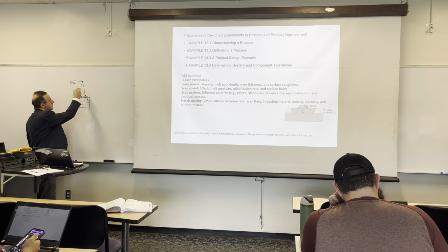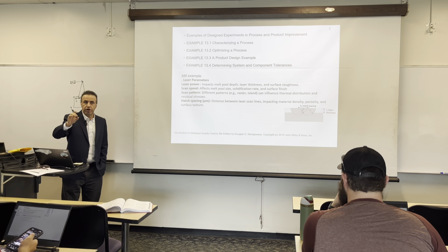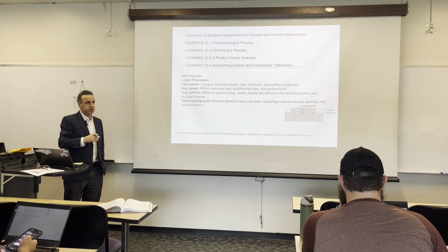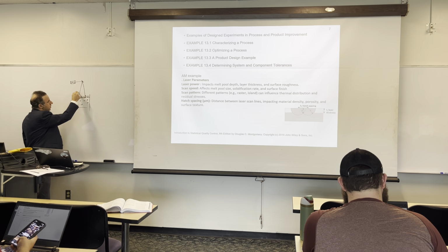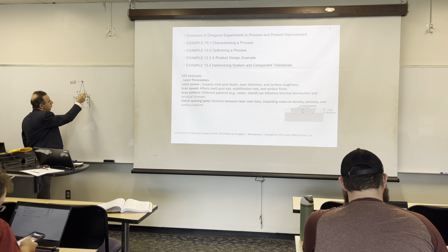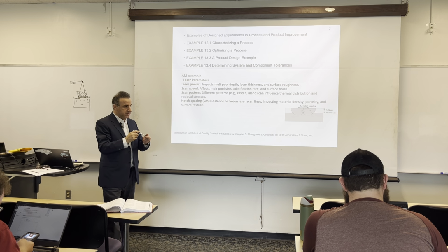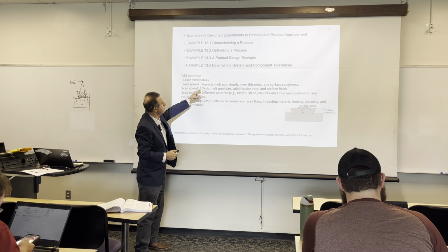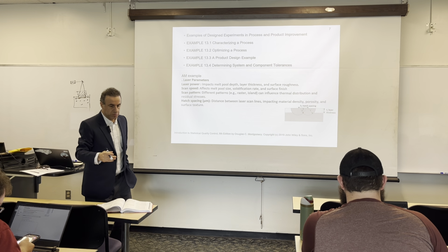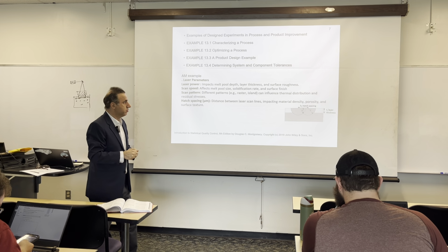And this mirror is going to repeat the process. Again, it melts the powder selectively, not the entire section, only in a certain area, depending on what your structure is, what your part is. So this is going to be repeated all over until you get a 3D part. So in this process, you have a lot of factors that are going to be involved. Laser power. The laser power should be sufficient to melt the powder.